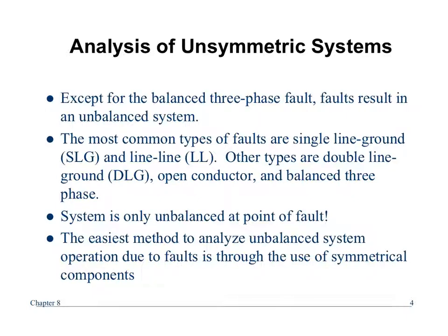If you do not do that, then symmetrical components, you can't employ that. That only works for a single fault, and we'll see that in a minute. Most common one we talked a little bit about, that's the single line to ground fault. But we do need to analyze line to line and double line to ground. Even though the worst case fault current is almost always going to be the 3-phase, there are a few systems and a few times when I've actually seen single line to ground fault that has a higher magnitude than a 3-phase fault. Not often, but on occasion.